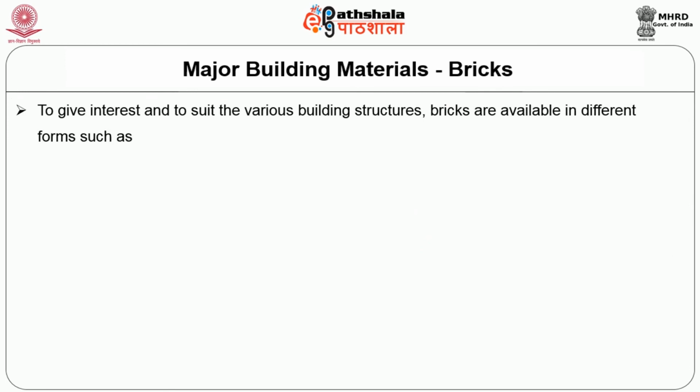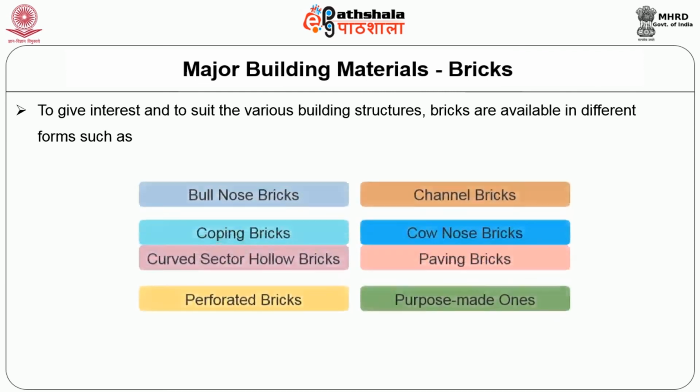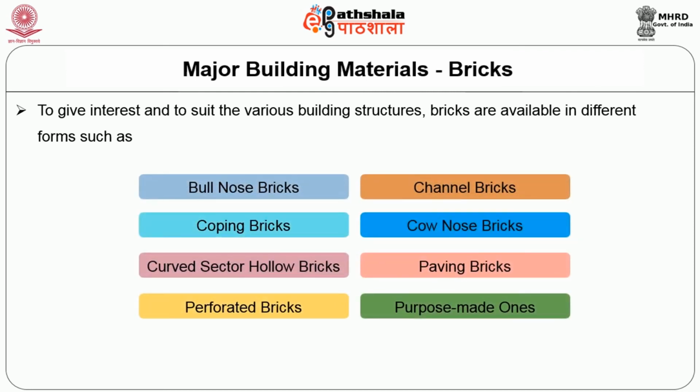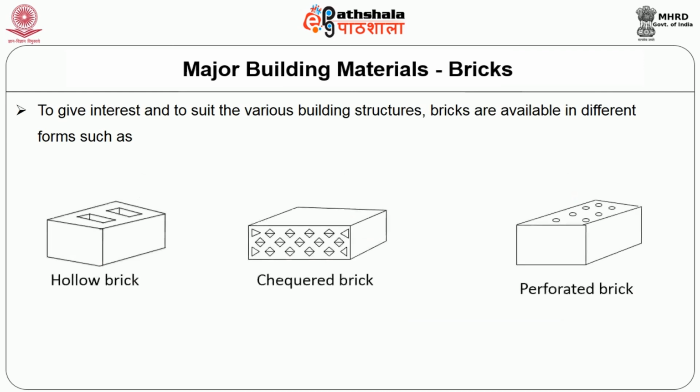To give interest and to suit the various building structures, bricks are available in different forms such as bullnose bricks, channel bricks, coping bricks, cow nose bricks, curved sector hollow bricks, paving bricks, perforated ones and the purpose made ones. We can see some diagrammatic representations of the bricks.